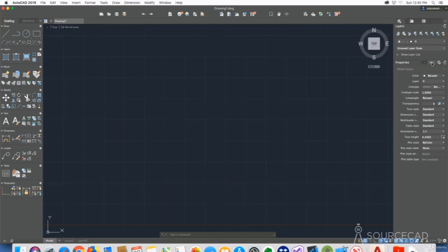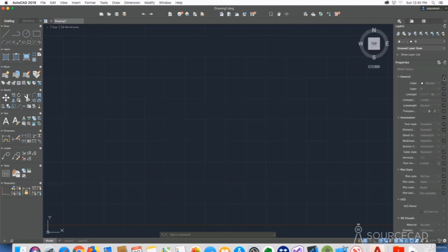Now this list is fully customizable. It's your list. You can just modify it, and you can add or remove properties in this list. Now to modify this list, go to this edit option and check the properties that you want to keep and uncheck those which you don't want to keep. So for example, in this case, we don't want to keep any properties related to plot style. So here I'll simply uncheck this first option on the plot style, and all the plot style properties will be unchecked.